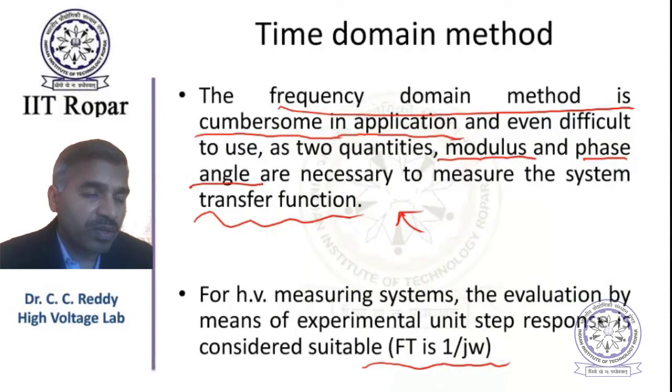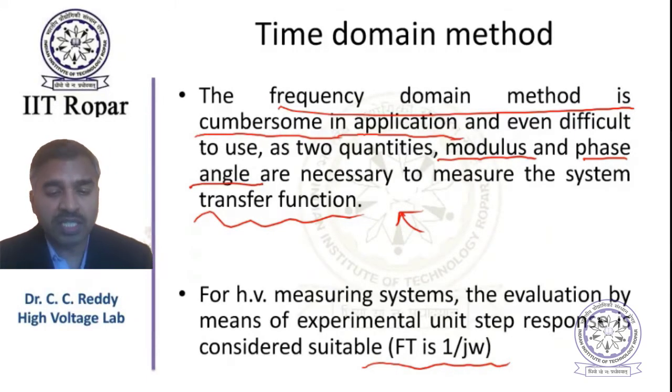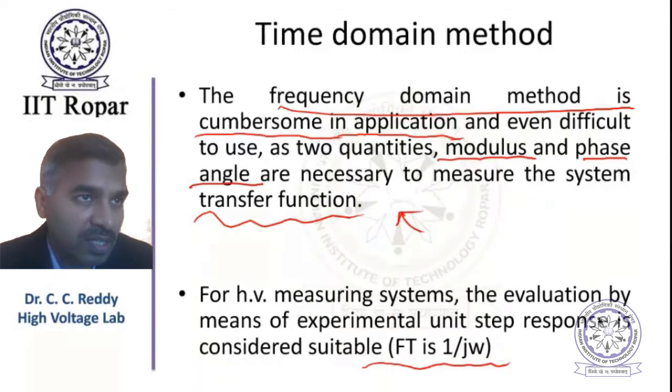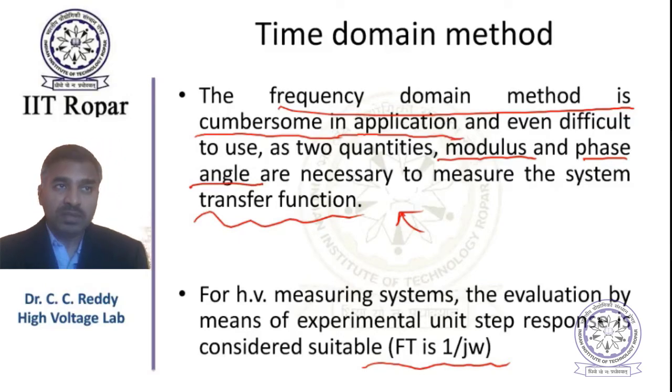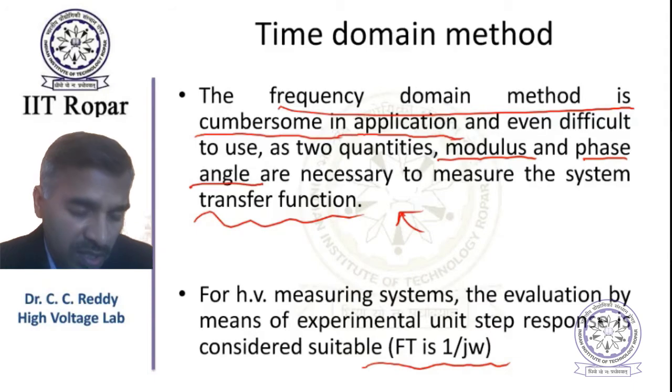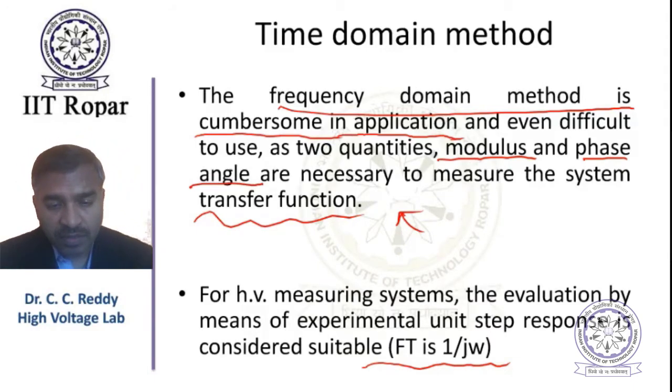These are all the problems which hindered the application of frequency domain methods. What we used previously, the chopped waveform, is a theoretical waveform, and we studied our frequency requirement with it. But we do not know what is actually the voltage applied at the terminals of the test object, generated by an impulse generator. So how to know the frequency components of that? Because the practical, experimental waveform does not exactly follow the double exponential function, right? Therefore, there may be certain frequency components or deviations resulting from the impulse circuit, or the load capacitance may be different, and then a little modification might have occurred. That kind of thing is not possible to know in advance. Of course, you will get a measured signal, but from the measured signal, how do you get the input signal?